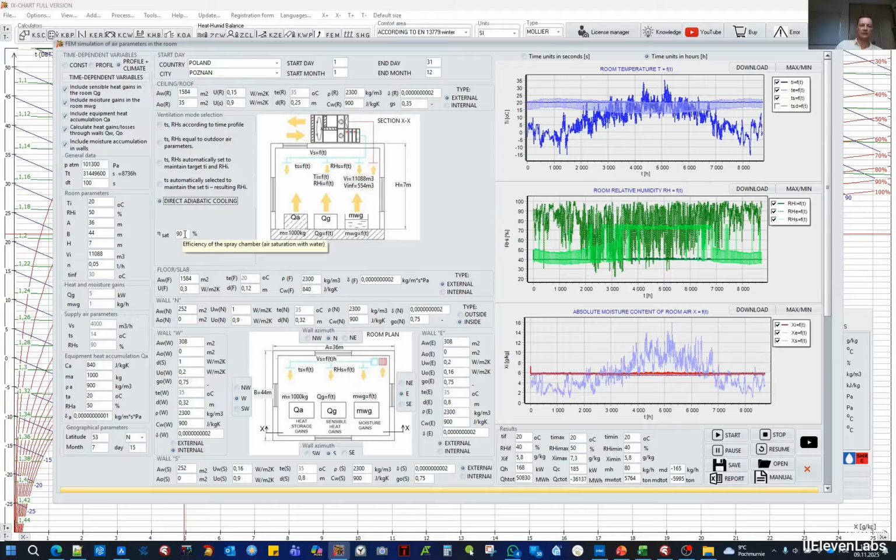An adiabatic process involves perhaps an exchange, because here we are not dealing with heat exchange as such. Here the enthalpy of the air remains constant both before and after the spray chamber, while the proportion between sensible and latent heat changes.